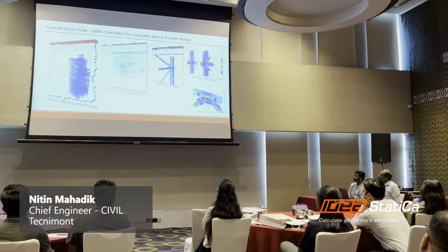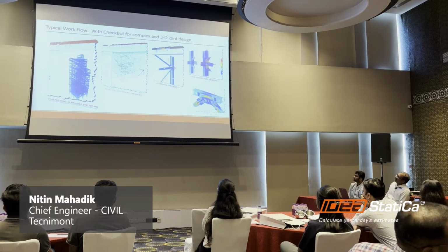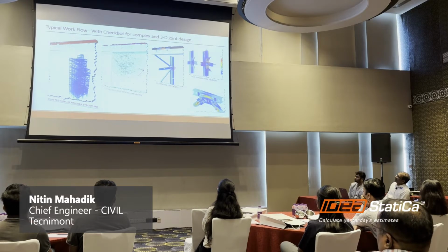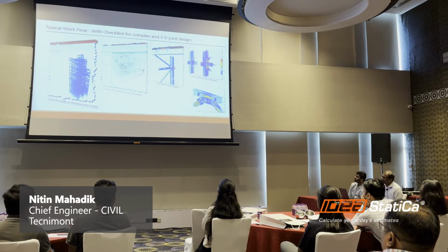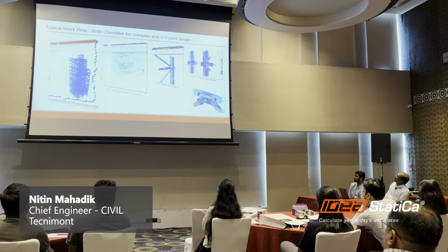So this particular workflow which we used in Tecnimont is the global analysis, which may be in STAAD or SAP. Then we pick one joint in IDEA StatiCa Checkbot. We import all those forces acting at the joint, which is in equilibrium. And these are the final connections. You can see the result of final connections.